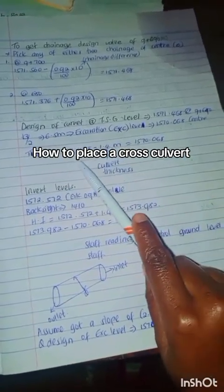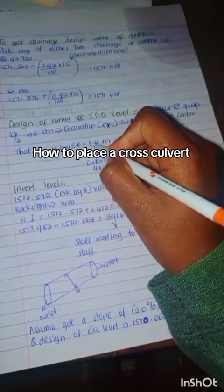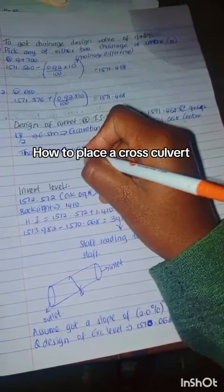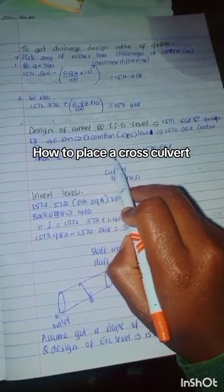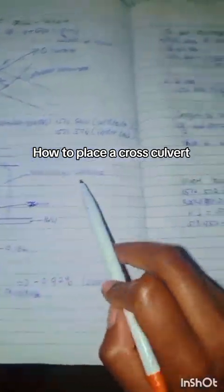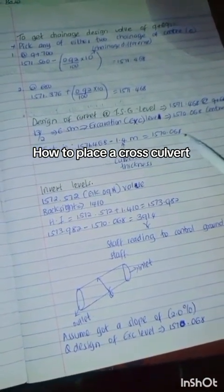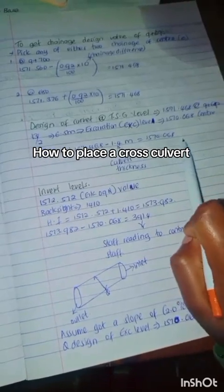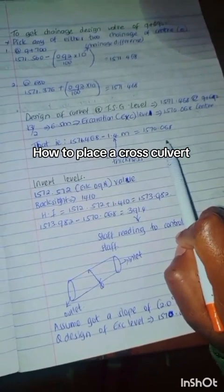So you take 1571.468 and minus 1.4 meters, that is the culvert thickness, the thickness from here just to the bed, and you get 1570.068, the excavation level needed for the center design value.